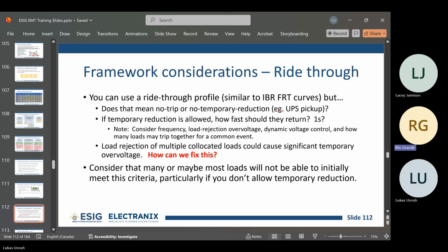Sorry, Luke. I was going to say, it definitely is possible. You would have a ramp rate requirement and just say, for this sort of controlled power shift, you're going to have to ramp down power slowly and come back up, which they don't want to do. For these AI facilities, that's well within the wheelhouse. It's not really a technical challenge, mostly burning energy on the way up and down. But that's one of those complex behaviors that could be something as simple as a requirement to notify your system operator that you're going to do it and then ramp down at a rate that I agreed to.